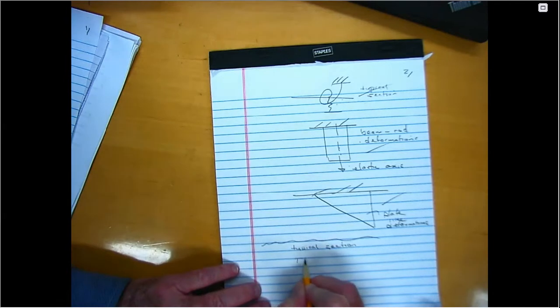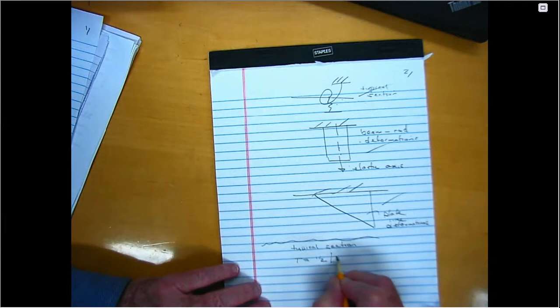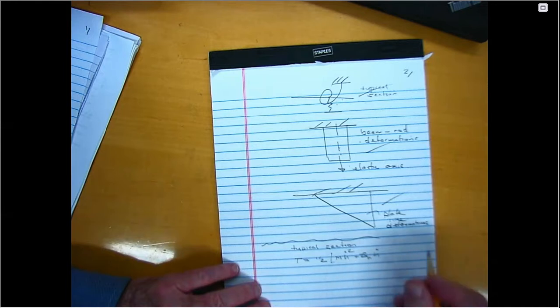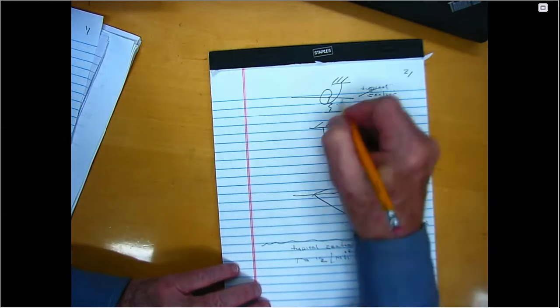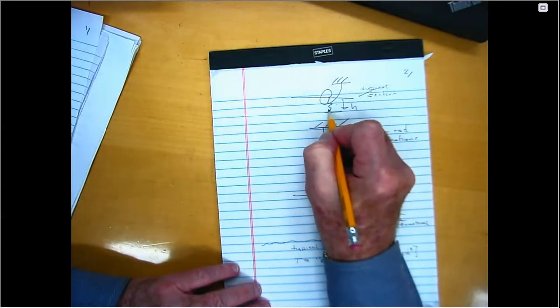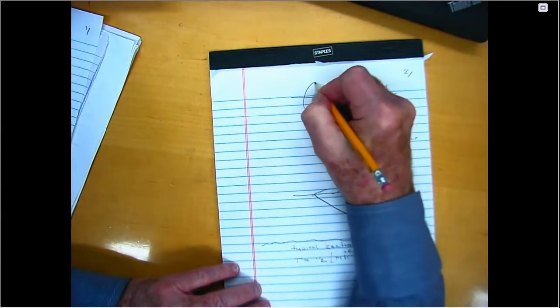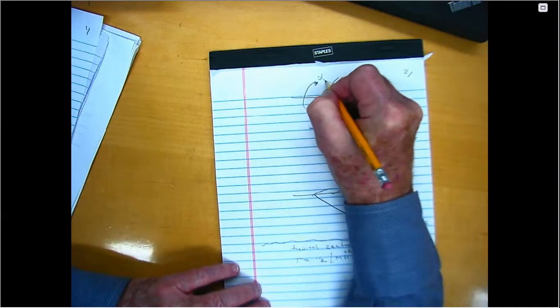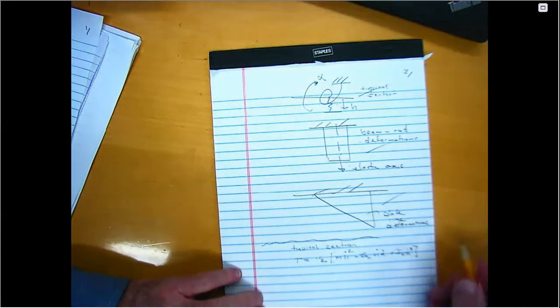I need to write down the kinetic energy, which is 1/2 m times h dot squared plus S alpha times h dot alpha dot plus I alpha dot squared, where we're assuming that we have a translation of this spring point down and a rotation about that spring point, positive nose up.